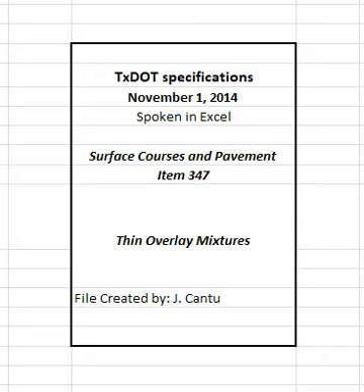The maximum allowable time for the contractor and engineer to exchange test data is as given in Table 5 unless otherwise approved. The engineer and the contractor will immediately report to the other party any test result that requires suspension of production or placement or that fails to meet the specification requirements. Record and electronically submit all test results and pertinent information on department-provided templates.